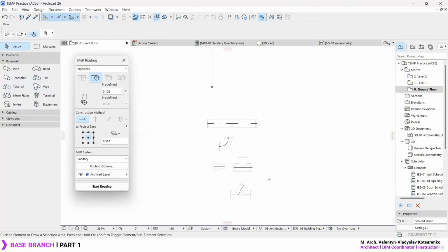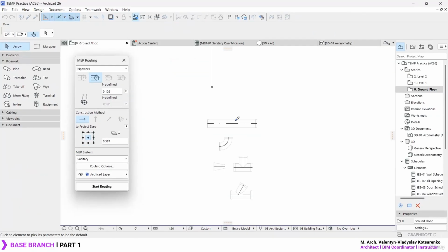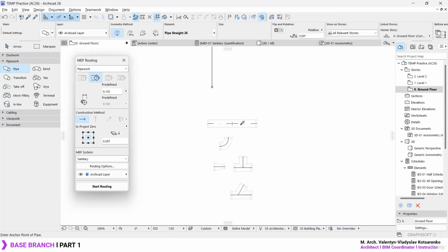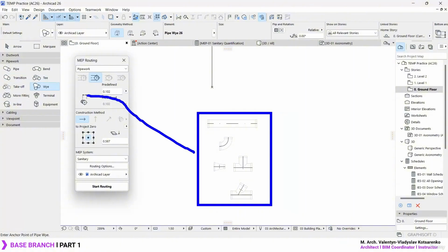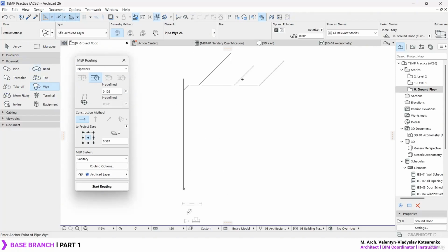And finally, but not least, the Y. So what I'm going to do is, just in case, so it works a little bit better, let's pick up the parameters for each of these elements. First for the pipe, next for the elbow, transition, T, and Y. So everything stays saved up, or the parameters of these objects will be saved up on these tools. Okay, and the pipe routing will pretty much also transition some of these parameters when we are drafting the branches.